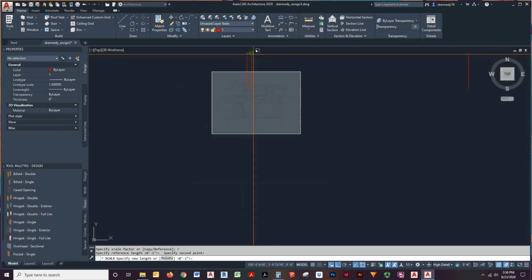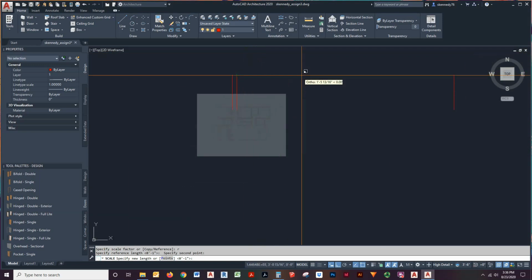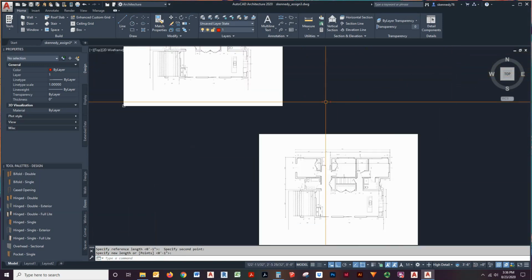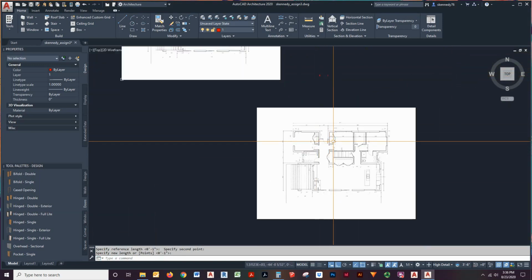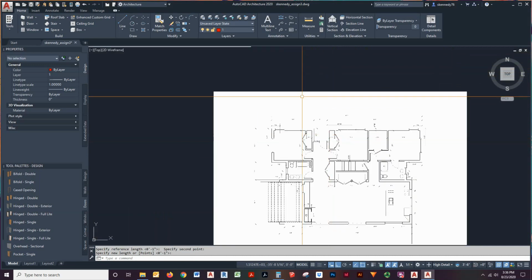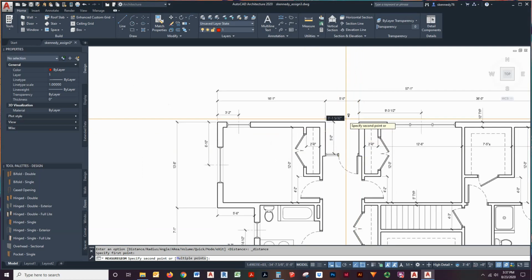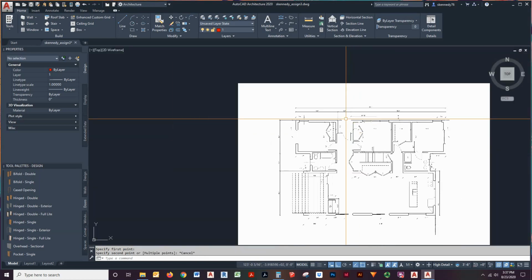And then I'm going to zoom out a little bit, so I'm using my mouse just so I can reposition, and I'm going to then select the 5 foot point. And if I zoom out, it now scaled this drawing properly. And if I just eyeball distance, just for real quick, yep, we're pretty close. I mean, you're never going to be able to eyeball something as accurate as AutoCAD can draw, but we will take this as being a pretty good scale.